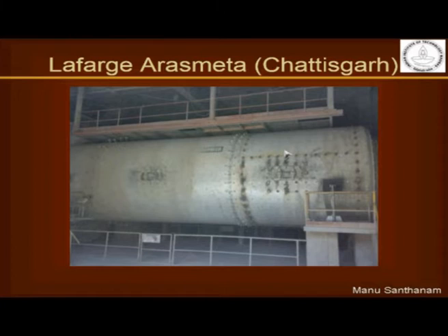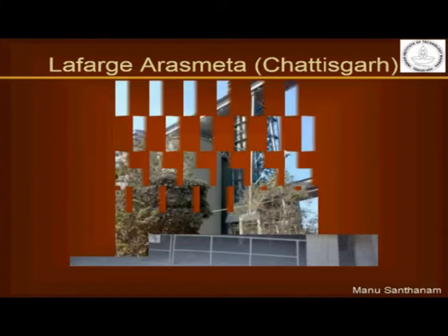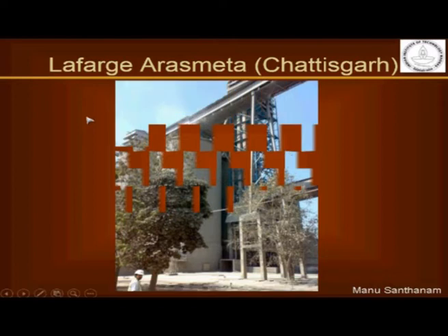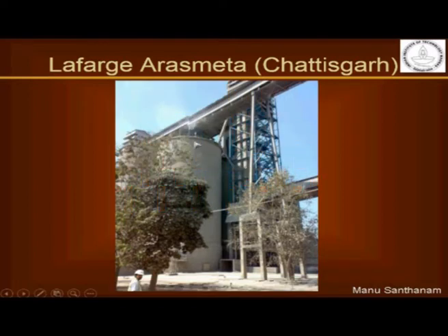So by impact you are crushing and blending at the same time. That's very important. You're not only crushing the material to the right size, you're also ensuring that there's a very uniform blend between the cement clinker, the gypsum and any other additives that you may put in the process. Okay, so these are the processes that are involved in the cement manufacturing. After of course you get the material out of the grinding mill, it goes to storage and finally packaging and shipping. So those are the processes that are involved in cement production.